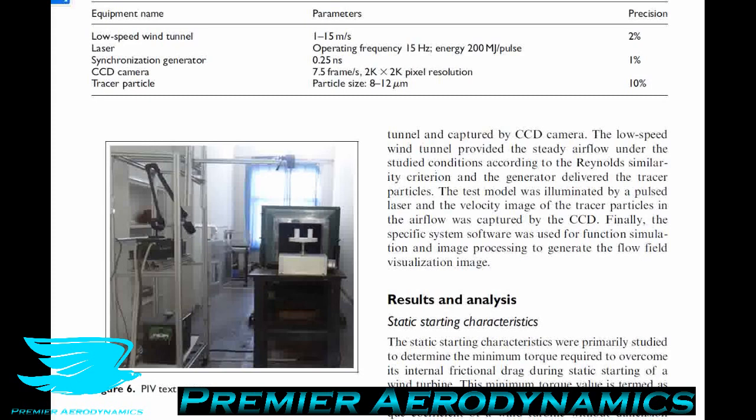The reason why is because if the speed is too fast, you won't be able to take 2 photos in the time it takes for the particles to travel through the laser sheet. So you take one photo, for example, and even if you take a second photo and you capture some of the particles, let's say 50%, that's still usually not enough to be able to do PIV, because then you're trying to trace where the particles have gone. But because so many particles have fallen out of that laser sheet, it's difficult to tell where these particles have gone. So you really want to have like 95% of the particles stay within this sheet during the time that you've taken these 2 pictures, which means you need to take the pictures very quickly or reduce the velocity of the wind tunnel. So that's why they went with 4 meters per second right here.